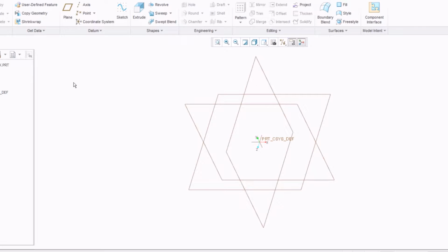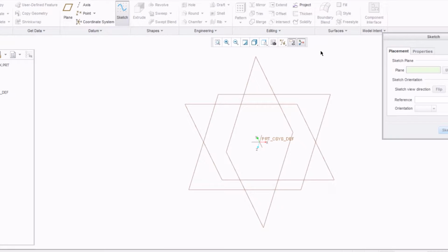As always, when you're making parts, it's important to consider how you're looking at them. So if you want to produce a part using the top view, let's say the top of a box, and you dimension the top of the box, you want to use the top plane. But for this example, we're just going to use any plane. Now I'll show you there's 2 ways of creating an extruded part. They're both correct, but one way is better than the other. So I'll show you both. The first way is to create a sketch. So you come up here, and click Sketch. It's going to ask us for a plane. We could choose any plane. We'll go ahead and use the top plane.